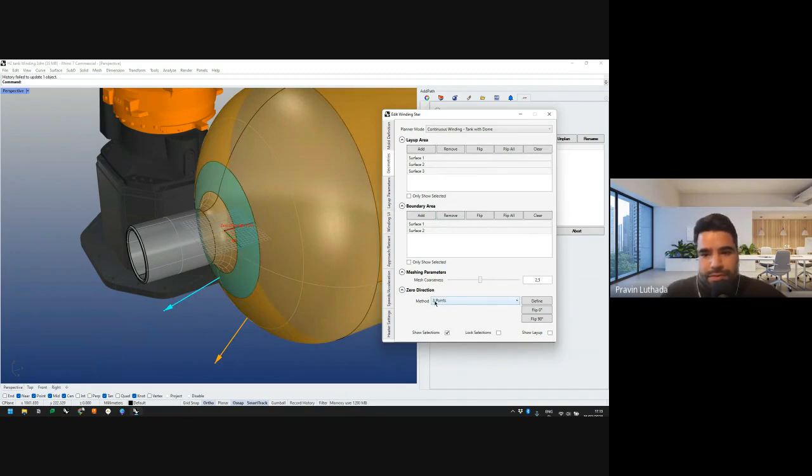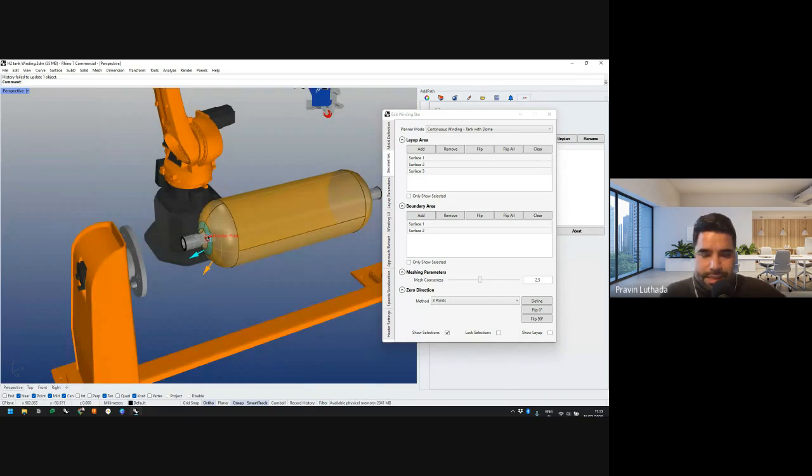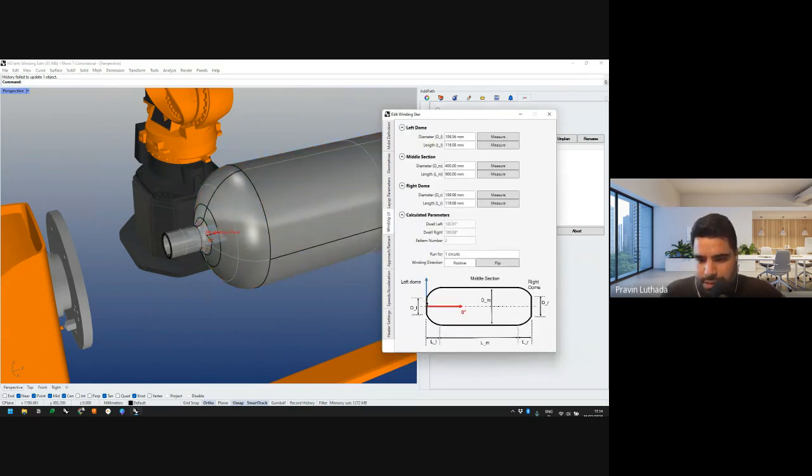So I need to make sure that I have defined my 0 degree at the beginning of the dome point, that is here. And then the dome beginning is here. So this circle center is what is defining my origin point. My zero direction is aligned with dome to dome center, and 90-degree has to be perpendicular to that. So this is very, very critical. As is shown here in the diagram, with the dome, it is aligned.